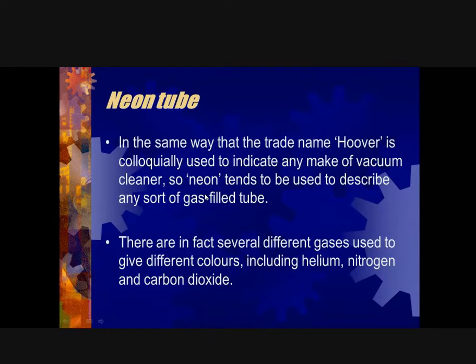It's actually an insulation resistance tester, but because Megger was one of the first brands of insulation resistance tester, people tend to say, let me get a mega, right? We need to use a mega to test the insulation resistance, but it's actually an insulation resistance meter, right?